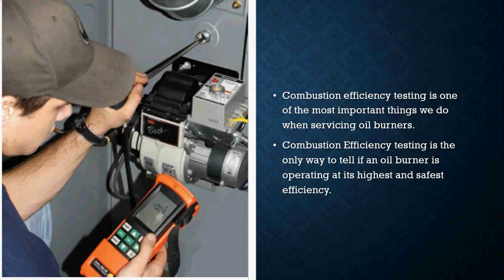You should do an efficiency test before you make any sort of adjustments and repairs to that unit, and then you should do another efficiency test after you have made any adjustments and repairs. Okay? Combustion efficiency tests are the only way a service mechanic can tell whether or not an oil burner is operating at its highest and safest efficiency. We have to make sure that these things are doing what they're supposed to do.